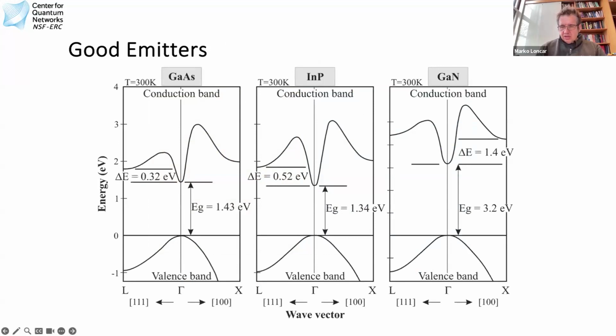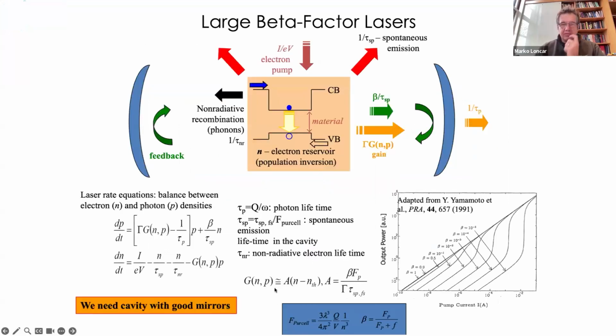In the context of a laser, when you want to build one, what you end up doing is you pick some semiconductor material, typically a so-called semiconductor heterostructure, where you put together two different materials with slightly different band gaps. The reason you do this is the electron can be trapped inside a quantum well. So you have some material that provides good emission, meaning this electron and this hole can recombine and generate a photon. This photon gets emitted. There's a probability of this photon being emitted in free space, and that photon is lost.